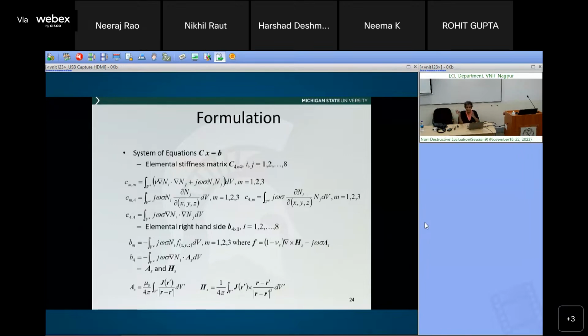Now I decoupled the geometry and the coil. So I have a module that will model just the coil, whatever the coil geometry, and calculate the field using just this equation. I just have to numerically evaluate these integrals. Once I do that, I have my source field. The source field is interpolated onto the sample nodes. And then I just solve it, that's it.